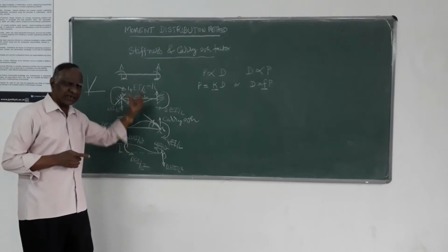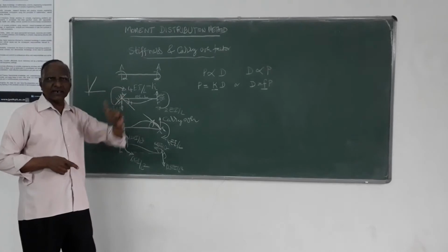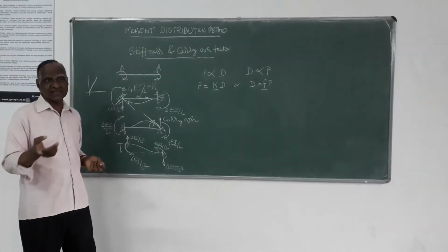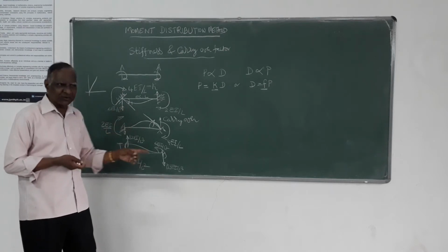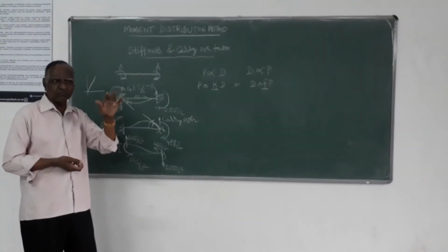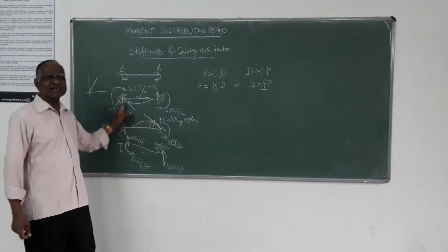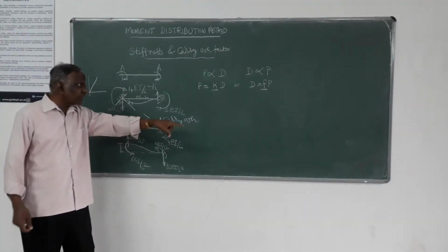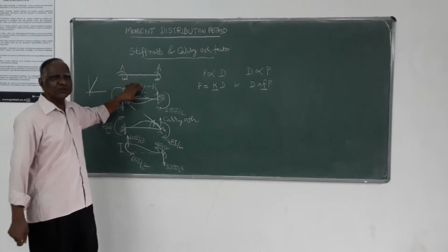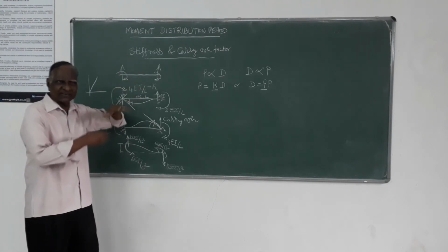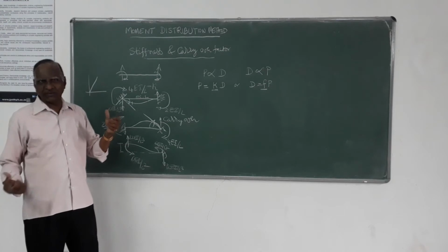So this is the basic principle of all the displacement methods of structural analysis, indeterminate structural analysis. This is exactly what we do in slope deflection also. By deriving the slope deflection equation, we use this stiffness. In the moment distribution method, indirectly we use this: we define stiffness for each member, and we use that rather than the slope deflection equation.